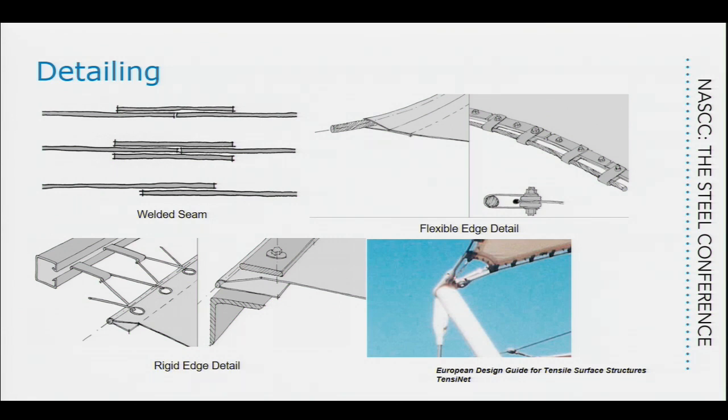For the welded seam, are you applying an epoxy or something? No, typically you could, and that's how they did it originally. But with the amount of force we need to transfer through there, the epoxies that were being used started dissolving the actual base material, because these are membranes. So most of the time it's done through infrared.